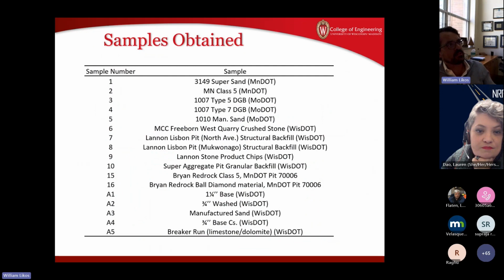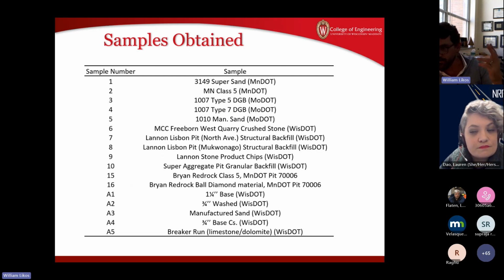Again, I think this is similar to the discussion we had earlier about granite versus limestone. I think the properties that matter are pore size distribution and compaction, as we just discussed. So hydraulic conductivity and water retention curves are going to be governed less by surface interactions than by pore characteristics. RAP is a little bit of a different animal. RAP has some interesting hydraulic conductivity and infiltration behavior. That one may or may not be applicable to this data set.